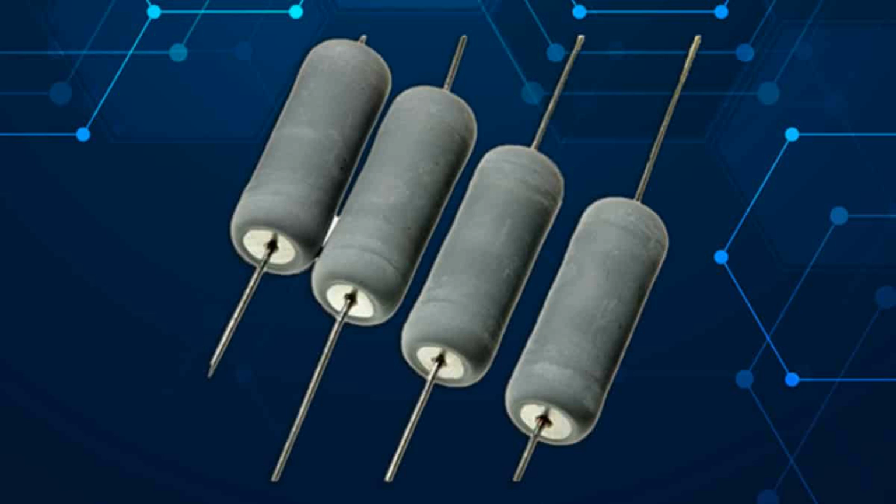Tolerance stacking. In circuits with multiple resistors in series or parallel, the tolerances of individual resistors can combine or stack to affect the overall resistance of the network. This should be considered during circuit design.